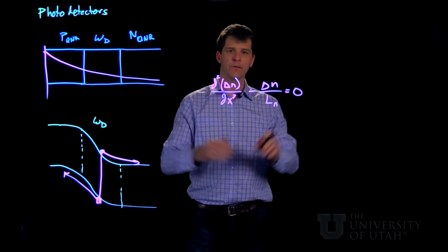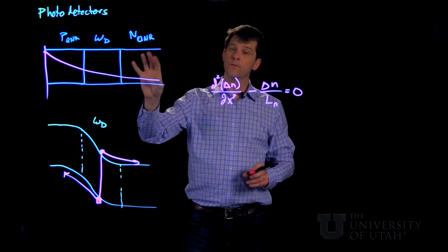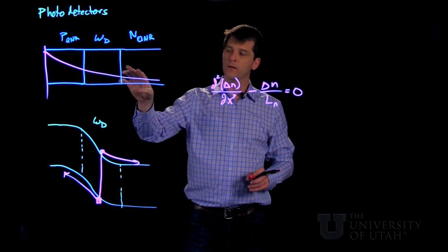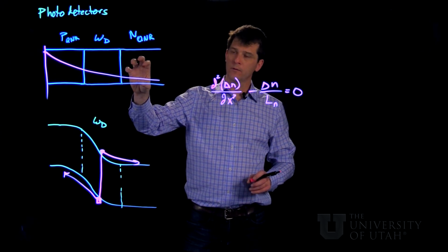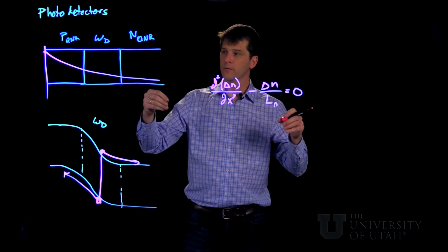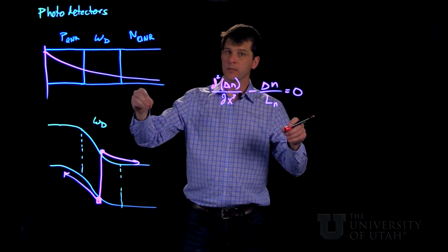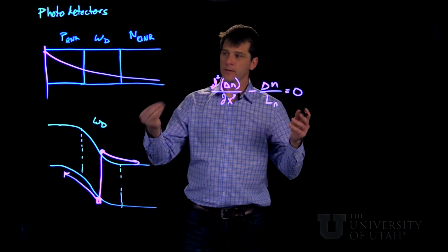So it reduces down to this form that we used previously for the recombination currents in the quasi-neutral regions under forward injection, forward bias, or minority carrier injection when we were deriving the ideal current of a PN junction diode.